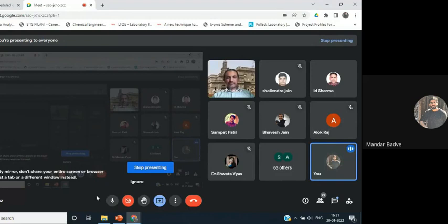Right? But if you're talking about implementing the technology at an industrial scale, then obviously you will have to operate using hydrodynamic cavitation, where your minimum volume requirements are at least 3 to 4 liters. Right? So it again varies with your application and your conditions. For just wastewater, if you're asking, then that is what I can say. I can't rule it out yet, and it is still useful, but for scale-up aspect, it cannot.